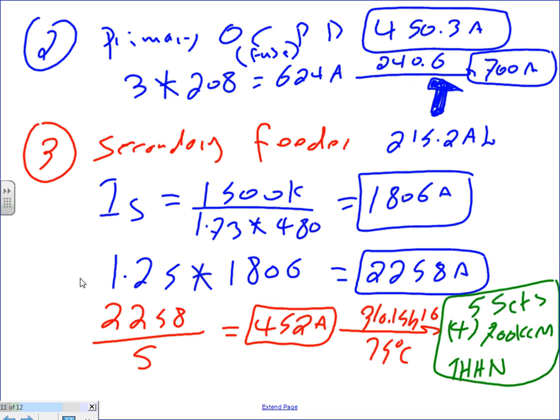I'd go to this one next in the industrial, guys. You add all the loads you're going to feed from a transformer, and then you find a transformer that can give you this load or higher inside your building. How does Excel size your transformer? You tell them what the service is. Remember the service calculation that we did? We came up with 500 amp.